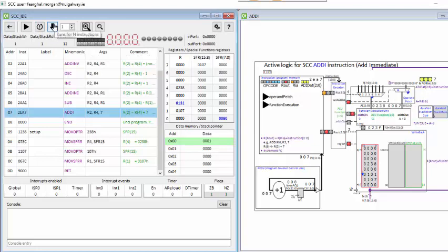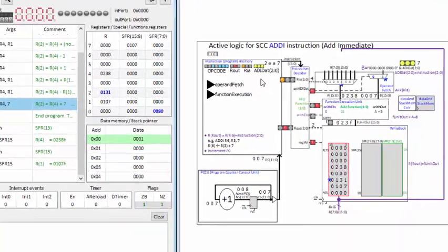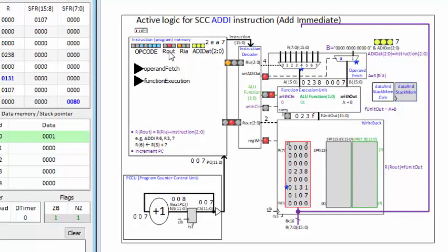And the last one is add immediate. Add immediate is a little bit different in that the output destination is R2 as before, RIA is 4, and it selects register 4 having been fed back through this multiplexer based on these 3 bits. But the instruction decoder also asserts a signal called sel ADI-DAT, and that selects onto the B bus the value instruction 2 to 0. Those 3 bits, 1, 1, 1, they're currently 7. I'm adding 7 to register 4. And I pad that with 13 zeros to make it a 16-bit value.